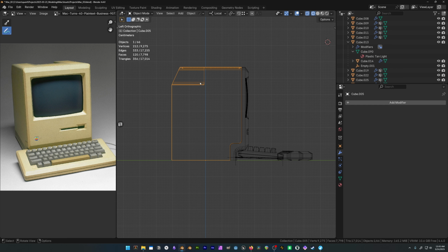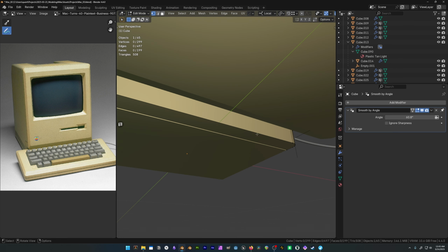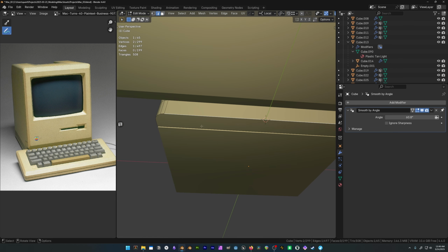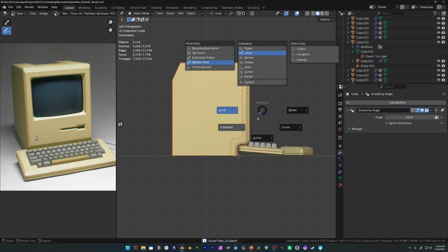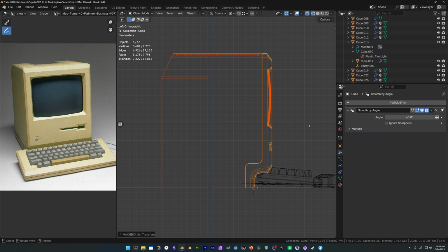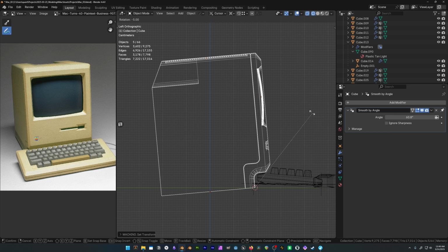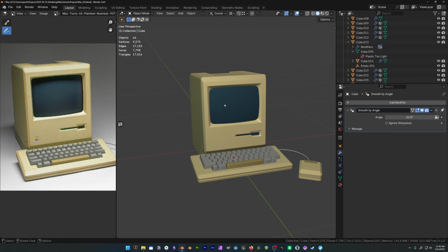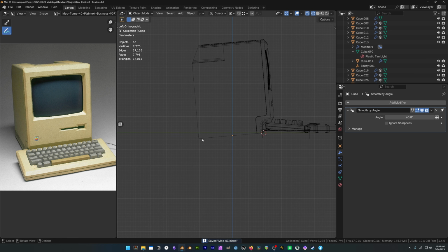And now I'm going to rotate it. I'm going to pivot it from the front. So I'm going to put the cursor where I want to pivot. I'm going to turn the pivot point to the cursor, and I'm going to pivot it a certain amount so I can always return it to the original. I'm going to go with 5 degrees. I'm going to save this.